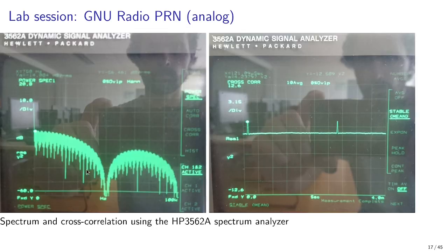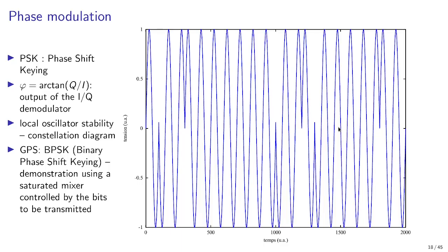This can actually also run on analog signal processing, such as the fast Fourier transform analyzer from Hewlett-Packard, which allows on both channels to analyze the spectrum spreading capability of the pseudo-random sequence, and by exactly taking the multiplication we've seen, calculating the time delay between correlations. So now that we are convinced that we understand how spreading the spectrum allows for time recovery, we need to understand the various steps for decoding GPS.